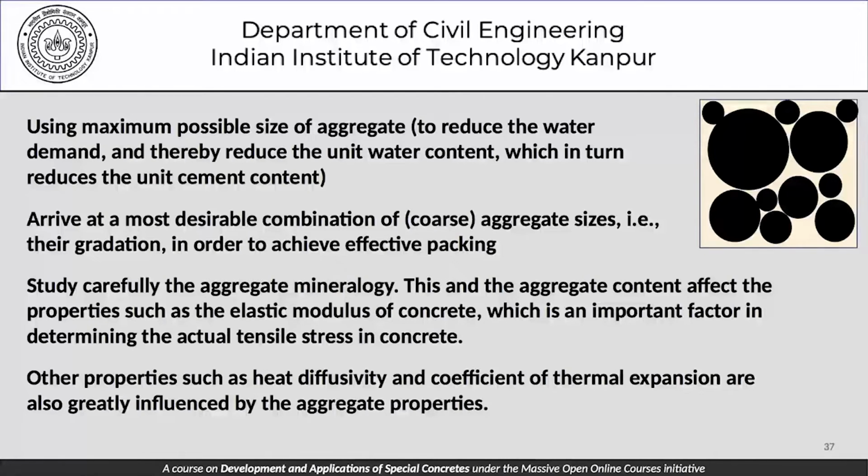These are some of the things or tricks, as I called them in the previous slide, that can be used in order to reduce the maximum temperature that is achieved during the hydration process. Yet another thing, of course, is we need to understand properties such as the heat diffusivity and the coefficient of thermal expansion, which is also greatly influenced by the aggregate properties.